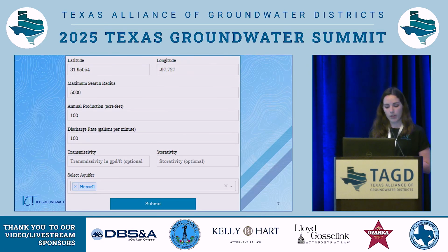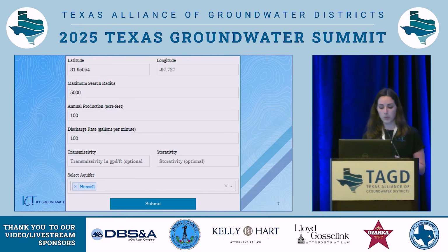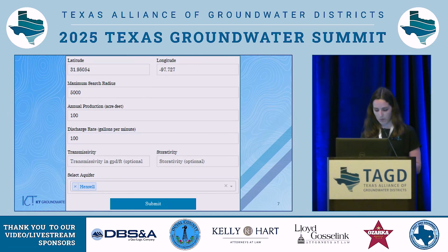The reason that we have transmissivity and storativity as optional is because although it is ideal to use these values from groundwater pumping tests, if you do not have data from that proposed well, this tool will pull on the GAM data and automatically fill in that transmissivity and storativity value for you. You'll also select your proposed aquifer, and then you'll hit submit.